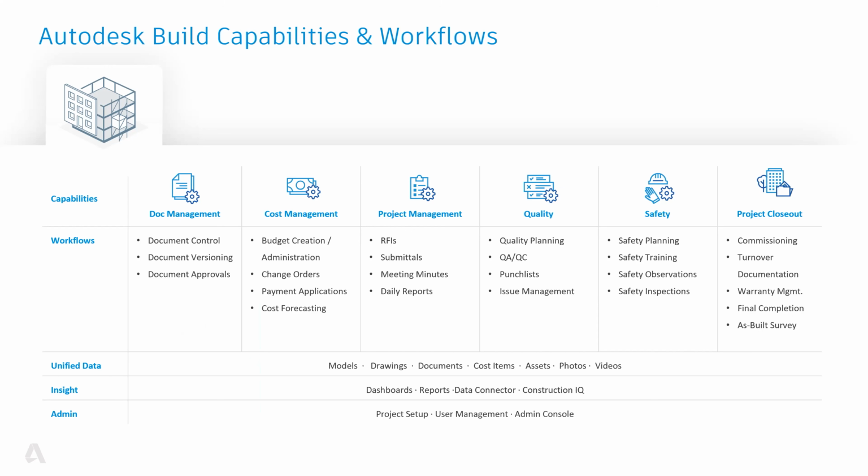Project management, so if we're looking at RFIs, submittals, meeting minutes, those kind of things, are going to be a part of Autodesk Build as well. And then the main bulk of Autodesk Build is going to be things like forms. So that will include quality, safety, and actually something that has been added very recently in terms of functionality, which is so recent I haven't actually put it into the PowerPoint, is the ability to create an as-built output. The idea being that you can essentially take everything that has gone to site along with submittals, RFIs, and output that as one lump file for a handover or just an as-built file format.